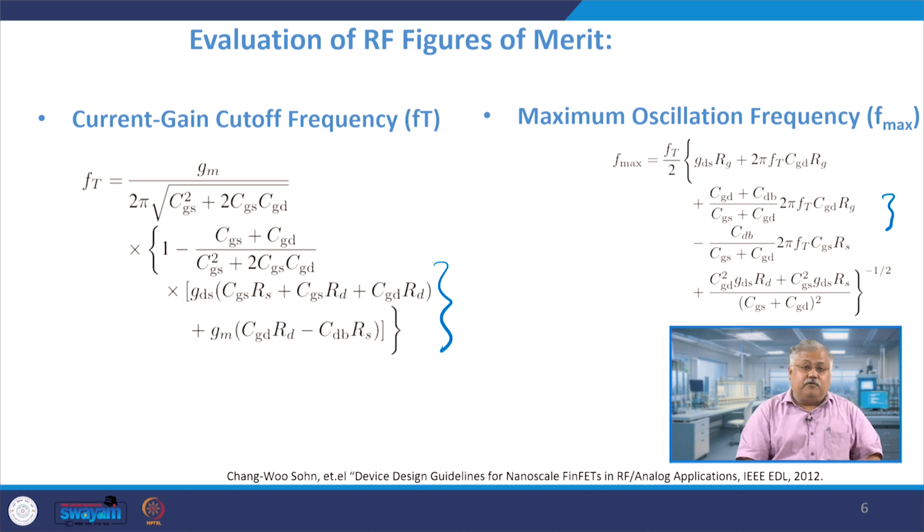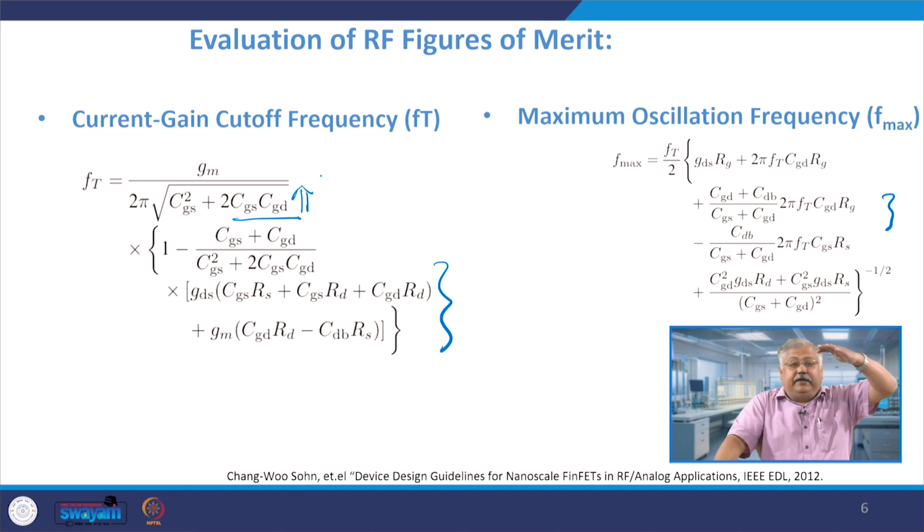you have larger number of fins, you typically therefore have larger transconductance available with you. But this larger transconductance will also make this CGDS and CGD go on increasing when your fin becomes either increase in height, or because of the non-planarity of the structure, the capacitance value will become larger and larger.